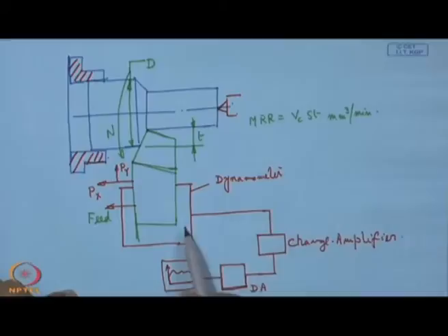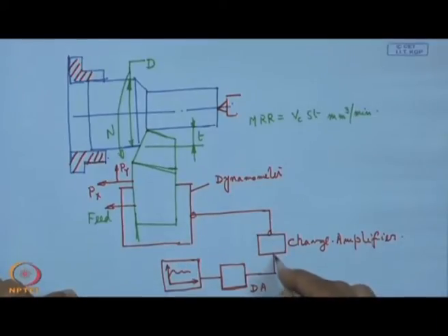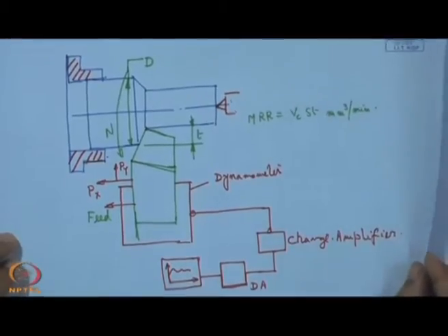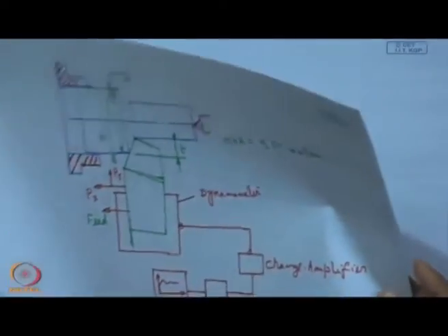So, the most important thing is that from here it comes to the charge amplifier. So, this is a charge carrying cable from this to this, and then we have a data acquisition, and from this point to this point the output is in volts. So, anyway, this is the force measurement. Now, how is this force measurement going to be beneficial? This is also another index of machining, in that we can also